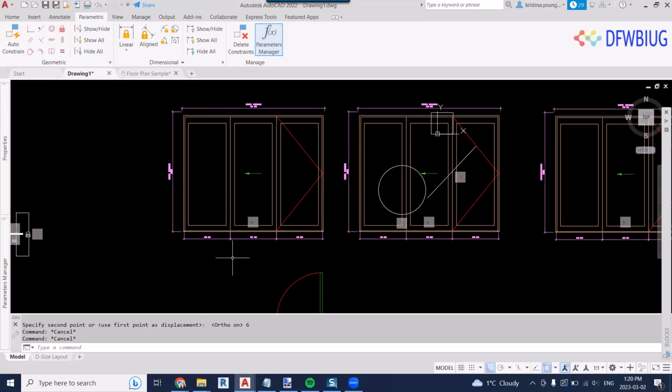We've got a lot of members that come on every day and every month. Tom had mentioned, can we use this for curb backspaces? Yeah, as long as you have a line that you can select and associate to, then you can set a constraint up to it. Make sure that it's drawn correctly. Is it a block? Is it a polyline? If you just have a bunch of lines, it's not going to stay associated. So pay attention to how you're designing, but it will also help you become a stronger drafter, because you have to stop and think: if I'm going to utilize these tools, I need to make sure that I've drawn this correctly. Otherwise, it's not going to work, and you're not going to get the results that you're looking for. And it is easier to draw correctly than it is to not.